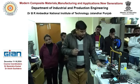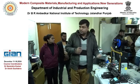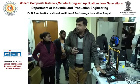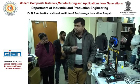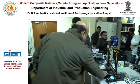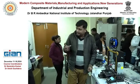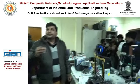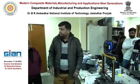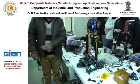Now the heaters are switched on and they are increasing the temperature of the extruder up to 200 degrees centigrade. Similarly, base heating also we have provided in the instructions, right? So now if you come and touch the bed, the temperature of the print bed has also increased to 50 or 60 degrees centigrade, right? Now it started moving along the X and Y direction.